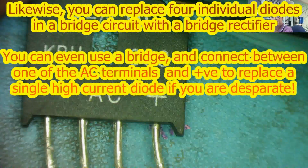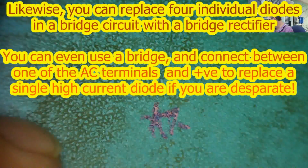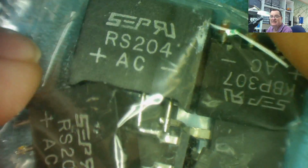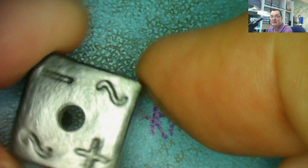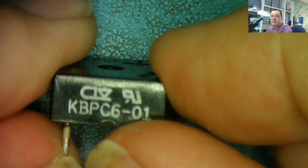To find the rating of this, you would have to look at the part number, KBU808, and find out what it actually is. We have some more. There's a few more in this bag. RS204, different ones. Again, AC are the 2 middle ones, plus and minus. Bridge rectifiers can get quite big. You can get some really quite large ones. This is a fairly small one, but you see how it's marked: AC, plus and minus. Almost certainly have a part number on it somewhere. There you go, part number, so you can see what it actually is.